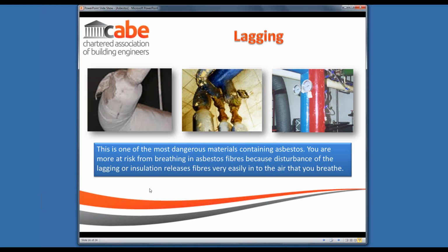Realistically, the asbestos register would identify the locations. You would then potentially come up with permits to work for those areas, conditions to work in those areas. As a belt and braces approach, I would suggest that it's a good idea to put notices in place, but realistically nobody should be working and operating in those areas without being aware that there's a potential issue.